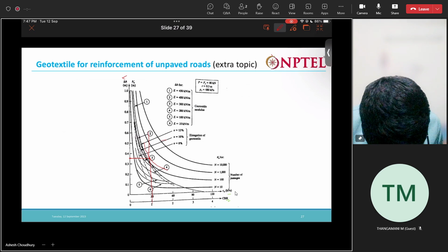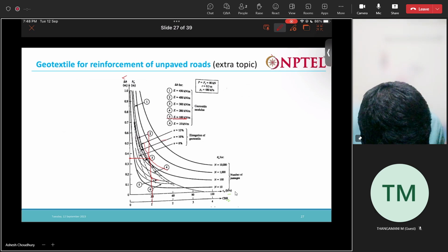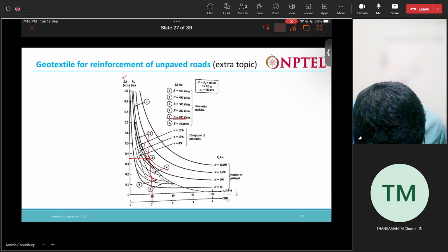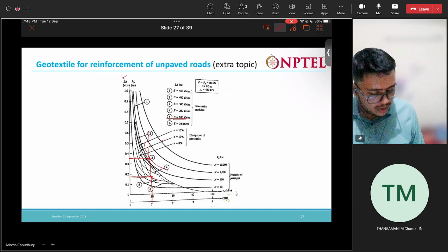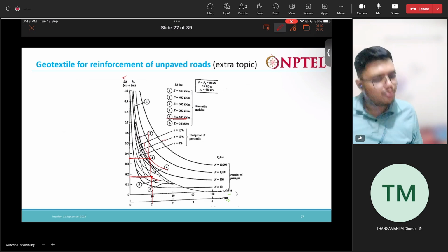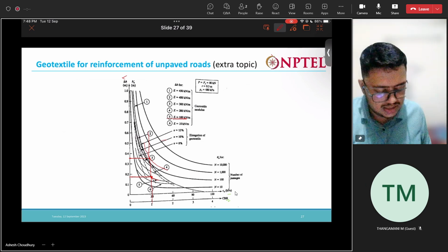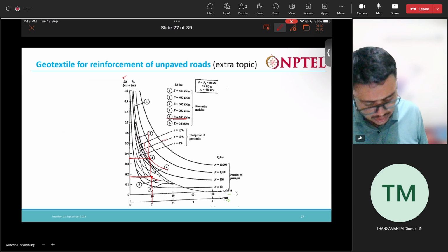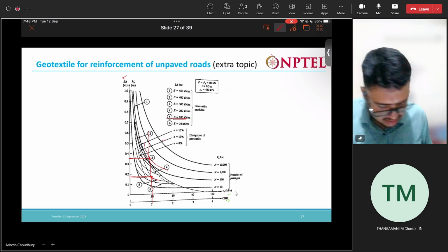And now when we use geotextile, we need to find this delta H. For that you need to use the graph. So E is 90, so we will use approximately 5 to this one here. So this one is approximately this. So you can see 0.18 or something. Right, so we got delta H as 0.16, but here approximately 0.13 or something is coming.